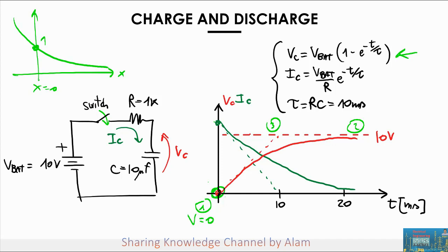And again, if you have a circuit where your supply is just a constant like a battery, the switch is not continuously operated, open and close, but once it's closed, for example, it stays closed forever, and the components aren't changing value dynamically. So the circuit is just constant and left to be, and you're just waiting for the voltages and currents to settle. For a capacitor, you can always say that the current eventually, after a very long time, has got to be 0.